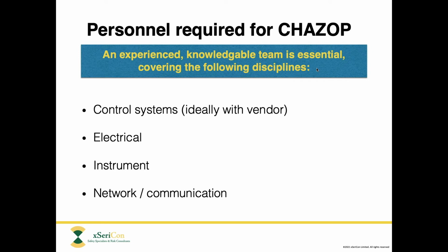So the chairman's job is to keep discussions on track, keep everyone focused on the purpose of the CHAZOP study, avoid long side discussions, avoid delays while people dig through documents trying to find answers, and avoid superficial answers or the whitewash that sometimes happens. These are all key tasks for the chairman in a CHAZOP study.